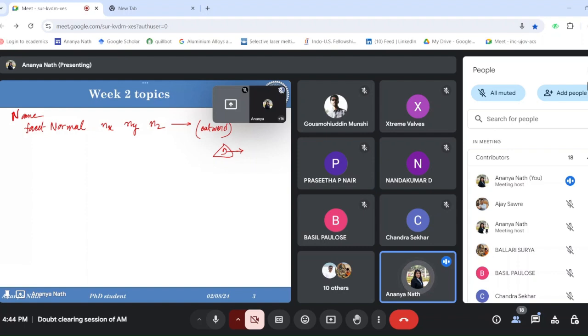Then after the facet normal we'll start the outer loop. Facet normal is this. Now we'll make the outer thing. For the outer thing, we will call it vertex. Obviously we are defining the points. So point 1, the x, y and z coordinates of 1.